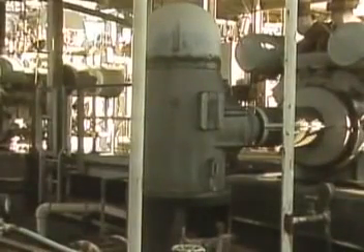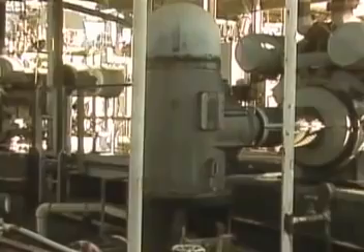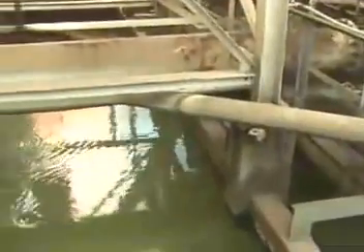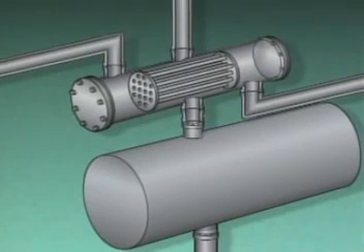Water can also be used as a cooling medium. The water in a water-cooled condenser has the same basic function as the air in a fin fan condenser. This is a simplified illustration of a condenser that uses cooling water to convert vapors into liquid. The condenser consists of a shell, tubes, tube sheets which support the tubes, a vapor inlet, a cooling water inlet and water box, a cooling water outlet and water box, and a distillate outlet. The illustration also shows a receiver.